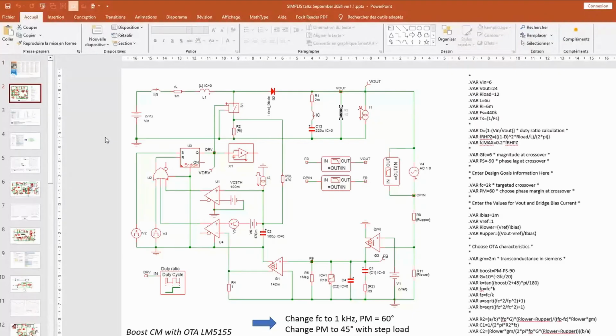So using a classical switch, very basic cycle by cycle circuitry, and then I test the electrical integrity of this circuit, making sure that it converges and delivers the right voltage and current at the given operating point. And once this is working okay, I start to enrich the models by putting in a MOSFET model, or a GaN transistor, because you can also import this type of SPICE subcircuit into SIMPLIS.